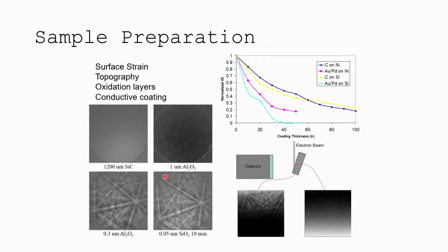And we can talk about how that works, but it's just standard metallography, right? Because when you polish with a 1200 grit, you're going to put certain scratches in it, but not only the scratches, you're going to have a deformation layer that's about the same depth as those scratches below. So you can end up with a nice mirror finish eventually, but you still have a lot of deformation in there, so you have to get rid of that.